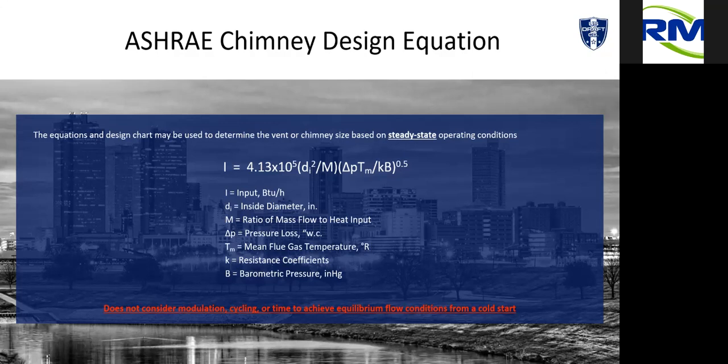And nowadays, we're not selling on-off boilers. Most of the boilers sold today, I would say probably 70 to 75% of what I see, are going to be modulating with a minimum 5-to-1 turn down. Okay. So that's obviously going to change the design equation just moment by moment. Okay. But it's a starting point. So we'll use that to start.